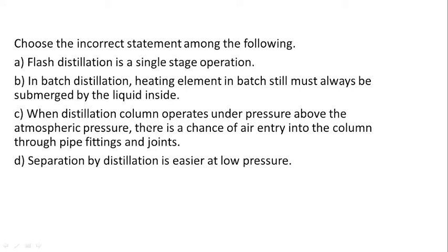Why is it wrong? When we operate the distillation column at a vacuum, then there will be chances of air entering through pipe fittings and joints. So it is not at a pressure higher than the atmospheric pressure.